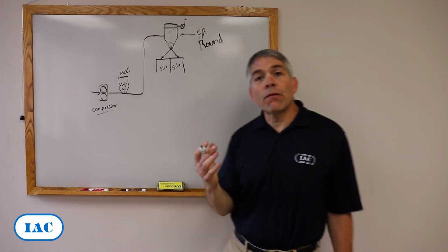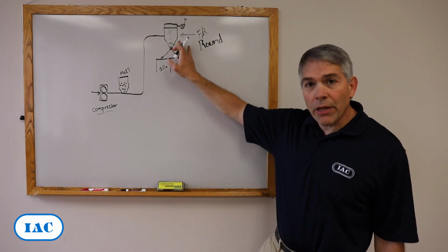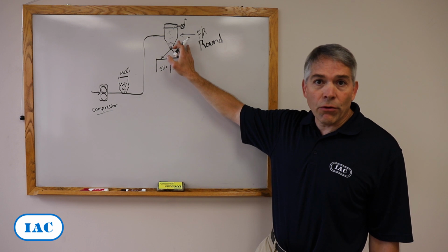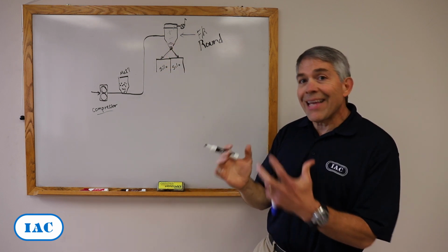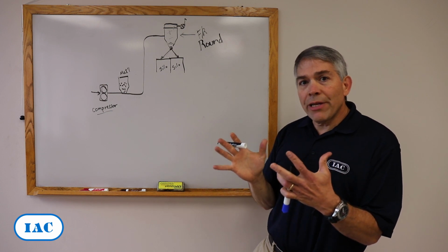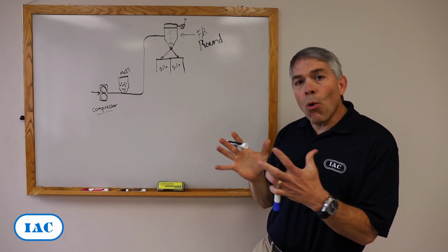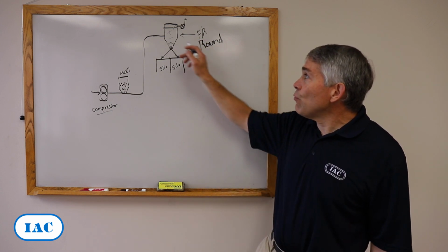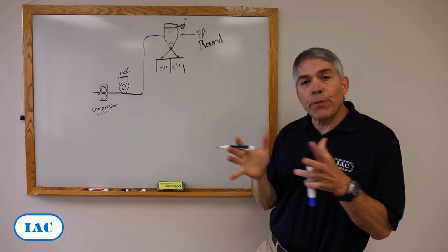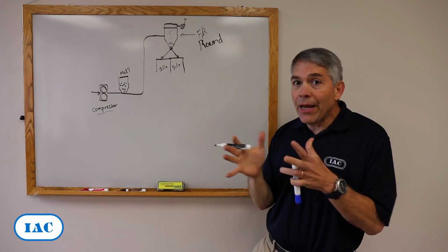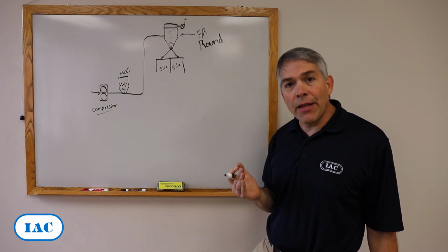We see a lot of installations where this is a dust collector because it looks like a dust collector application, but it's not. A dust collector is very much steady state, pressure is usually negative, and it's not subject to oil canning. So a baghouse is usually a square housing, and in this application it suffers because it oil cans. It goes positive and negative, and eventually you get cracks in the housing.